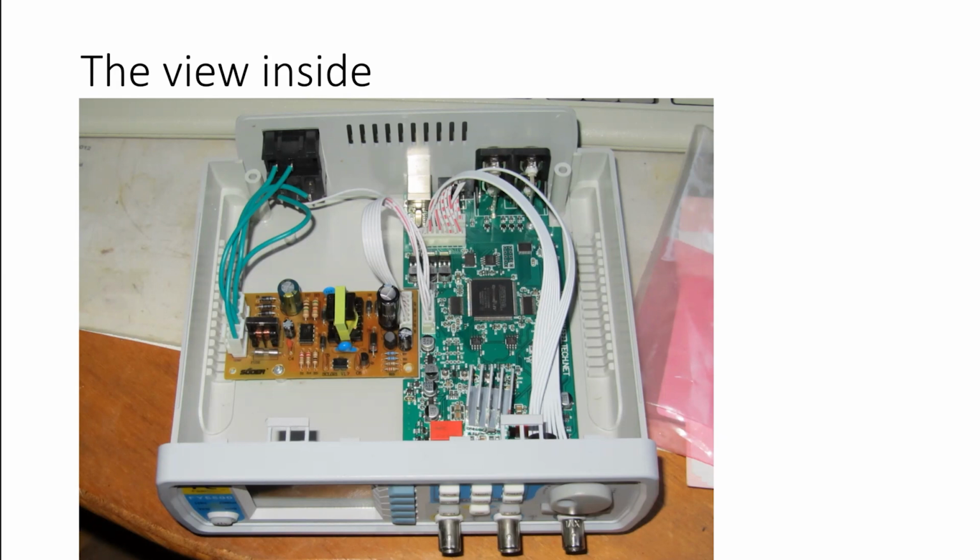Looking inside it, you can see the back panel there with the power input and some signal inputs. And then there's the Paxolin power board. Paxolin is that brown synthetic resin bonded paper, SRBP board, that power boards are very often made out of. It's cheaper than the FR4 and it has better characteristics for making power supplies out of. So power supplies very often find themselves made up on these brown boards. So that's the power supply.